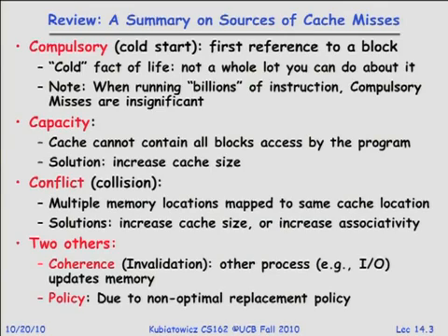Question, yes? So there's a copy of the same entry in the cache in both processors? Yeah. So in this particular scenario, caching is used on both processors. They both at least have a first level cache. And if processor A loads something into its first level cache and processor B writes it in its first level cache, we now have inconsistency unless somebody takes care of it. And oftentimes there's hardware that takes care of it. And so that would be a coherence miss when you go back to look for it.